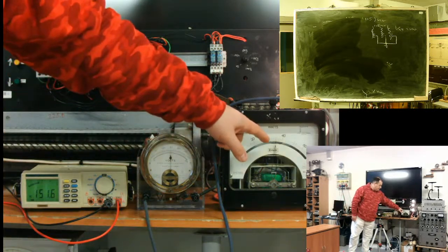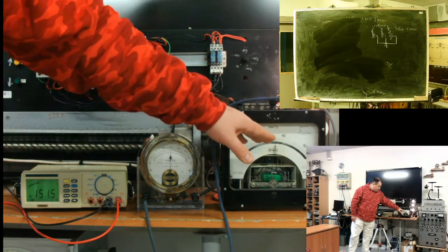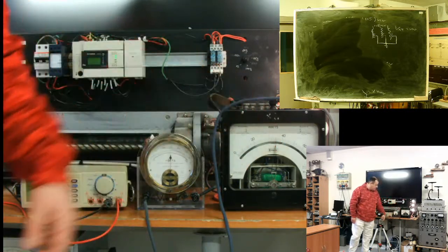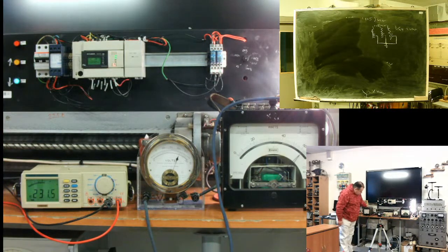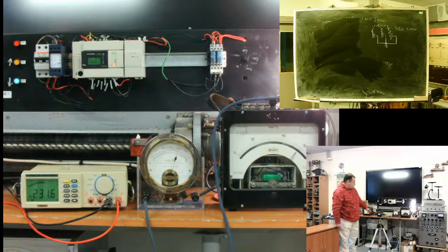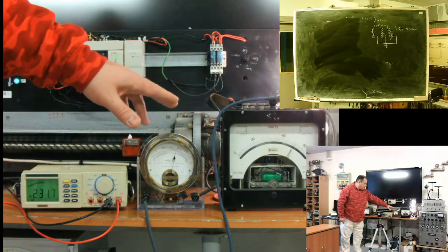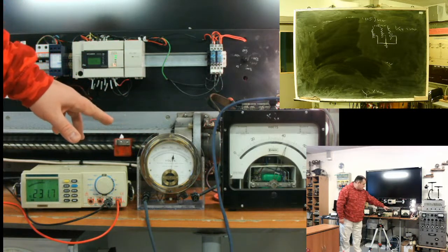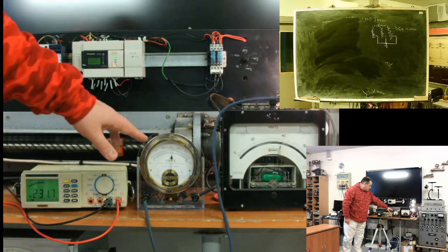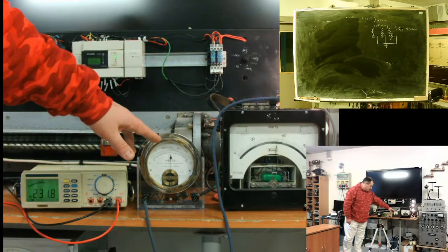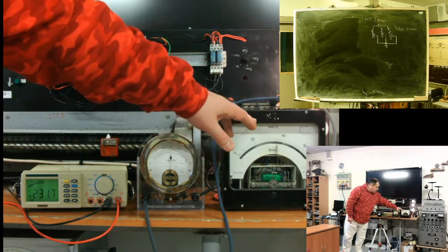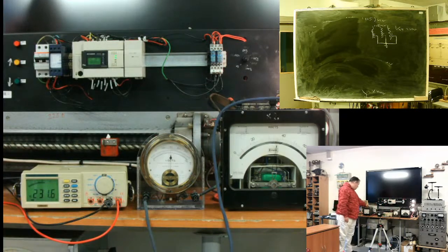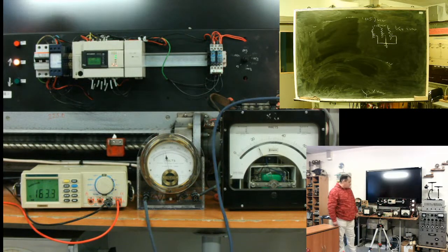And look at the load power. 35 divisions, it should be multiplied by 2, so it's 70 watts. Take a look, I increased voltage to 230. Look what's going on. First we saw power increase, but the control system places it back. The control system returns voltage to the set point. You see power returned to the same level. I decrease voltage, power increases.